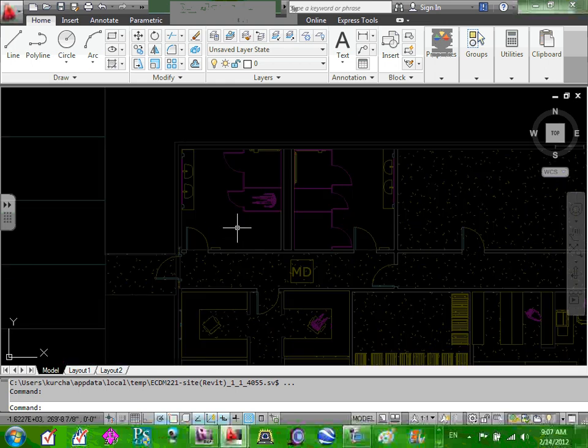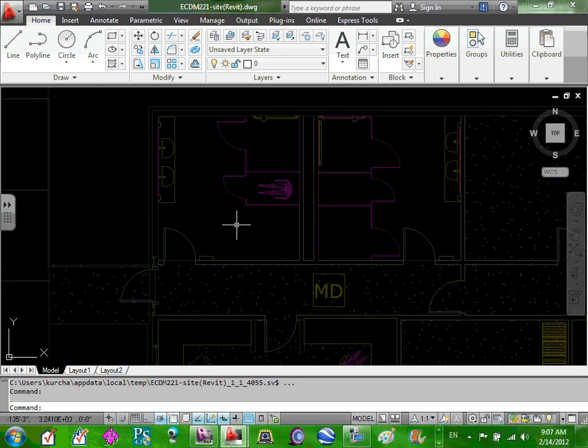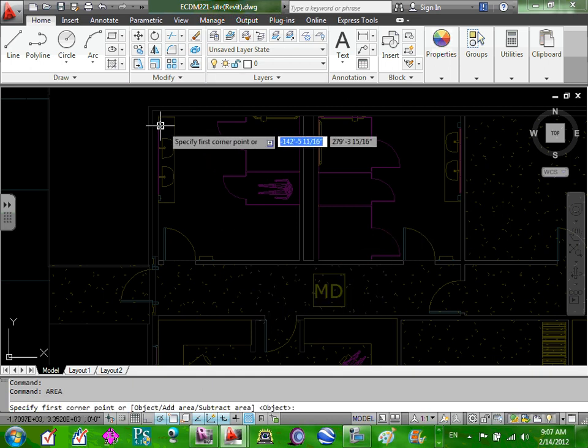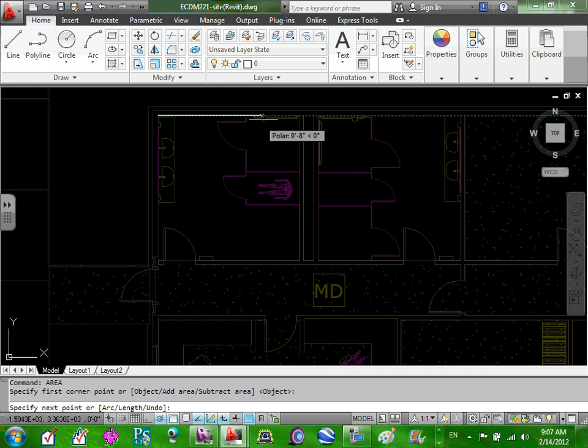If you guys go to, here's my bathroom, Ashley. Look at this, right? If you go to CAD, there are two ways to get the area. You can print it to scale and measure it, or you can go to CAD and type area. When you type area, click, and then you can pick the area of your bathroom. Since these are all bathrooms, I'm going to put my ortho on.